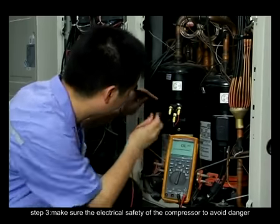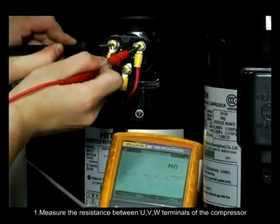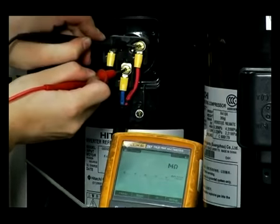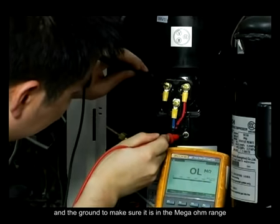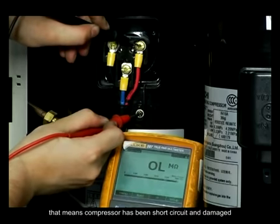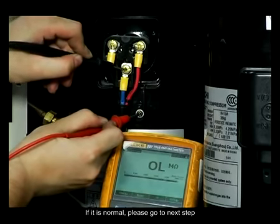Step 3. Make sure of the electric safety of the compressor to avoid danger. 1. Measure the resistance between the U, V, W terminals of the compressor. The resistance should be equal, between 0.9 and 5 ohm. Measure the resistance between each of the 3 terminals, U, V, W, and the ground to make sure it is in the mega ohm range. If it has only several ohms of resistance, that means the compressor has been short-circuited and damaged. Do not connect the electrical control and change the compressor directly. If it is normal, please go to the next step.